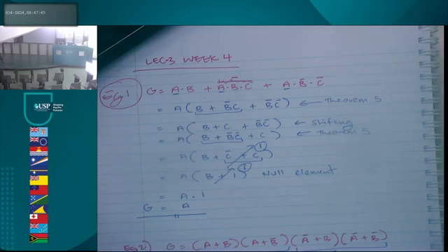6 gates. And in the end, after applying Boolean algebra, all those Boolean theorems which we have become familiar with, we end up finding that G is equal to A. So instead of going through this big circuitry which has 6 gates, we just connect A to G. All that circuitry is eliminated. So how many gates do we end up with in the end? Final answer. We go from 6 gates reduced to how many? 0, right? So that's a total cost savings. So your total costs have been saved, all right?